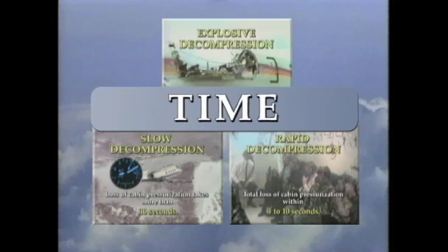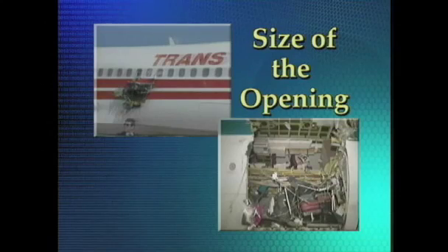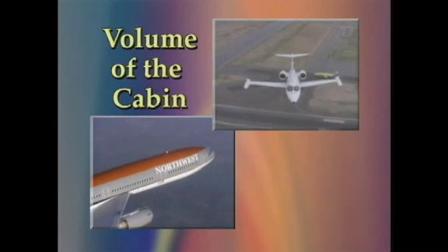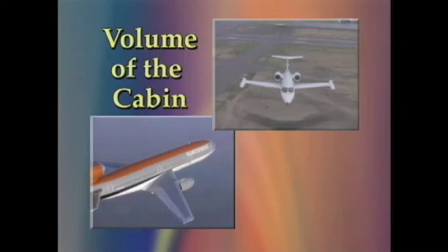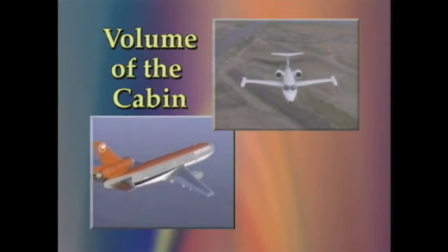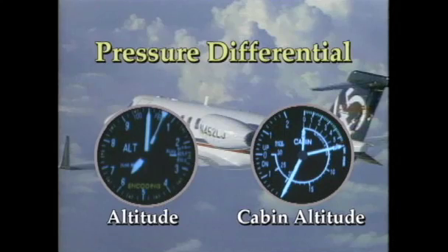However, there are other factors that contribute to how fast an aircraft will decompress, and they can affect time. These factors include size of the opening in a damaged aircraft. The larger the opening, the faster the decompression. Volume of the cabin. The larger the cabin, the slower the decompression, with all other factors being equal.